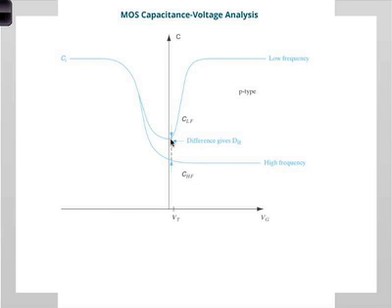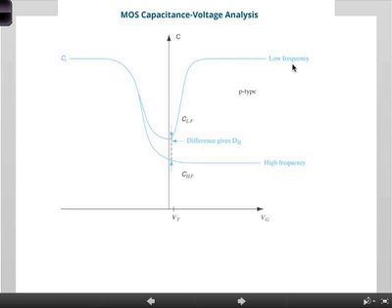Okay? So this inversion is the largest, and you need to take that into account. After that, strong inversion comes in, and then it becomes N-type, and the majority carriers contribute, and the capacitance goes up. This term goes down, essentially. This whole term basically gets ignored, and the capacitance goes up to the oxide capacitance again. So that's relatively straightforward to understand. This is low frequency.